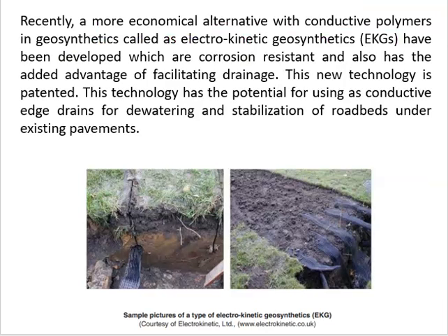Recently, a more economical alternative with conductive polymers in geosynthetics, called electrokinetic geosynthetics, has been developed, which are corrosion resistant and also have the added advantage of facilitating drainage. This new technology is patented. So this technology has the potential for use as conductive edge drains for dewatering and stabilization of road beds under existing pavements.